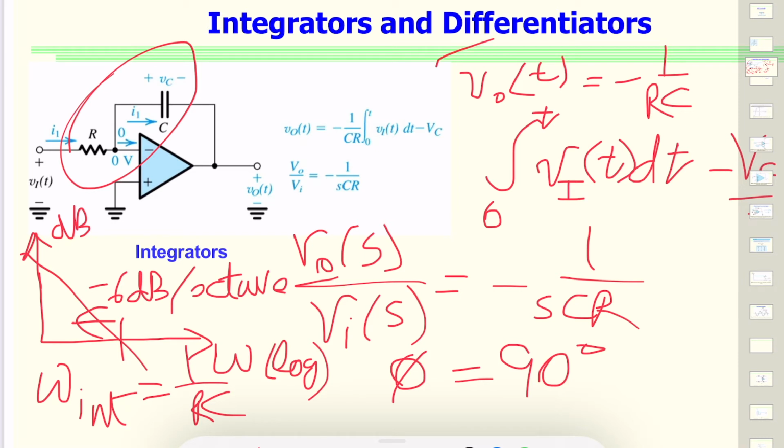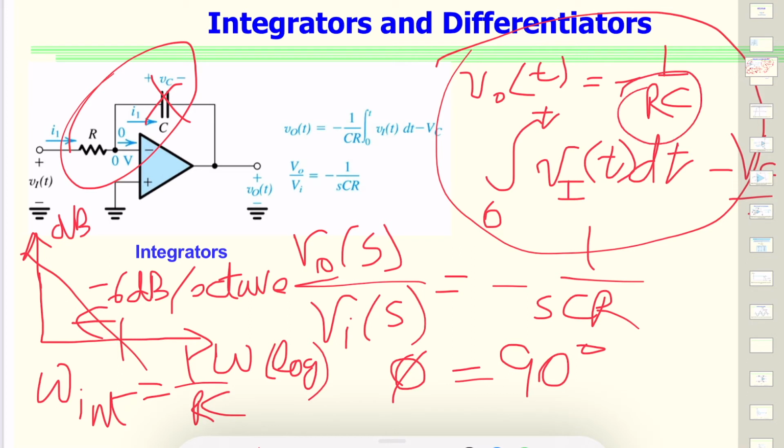If you look at this and you plug in a capacitor to be an open circuit, which would be for DC, in that case, that would mean there will be no negative feedback, and it will have infinite gain for DC, which would mean if C is not there, you get an open circuit, and there is infinite gain. Of course, it will be restricted by the saturation, which we saw, L plus, L minus, this power supply voltage.